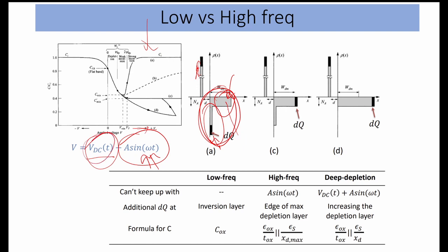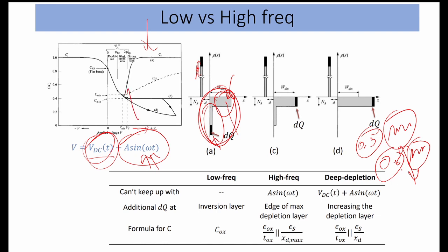So how are we measuring? We have applied a 0.5 volt DC, and at this voltage we apply the sinusoidal wave, and then at 0.6 volt we apply the sinusoidal wave. How this behaves because of this small signal is what we are taking in the CV characteristics here.